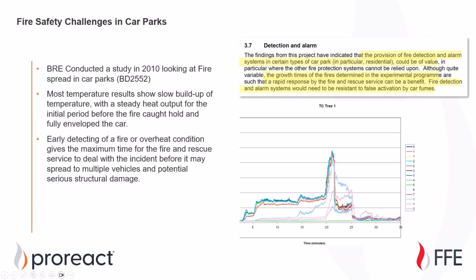And the British compliance body, BRE, had conducted a study that there is towards the first 5 to 10 minutes, even up to about 20 minutes, when you have scenarios like this, kind of a build-up period where your temperatures can be detected, like an overheat condition with linear heat detection, during these times to notify somebody that attention is needed in these areas, and potentially have saved this fire from becoming what it became and destroying all that it did. So linear heat detection is in the conversation with a lot of the development that's going on with codes and standards when it comes to parking structures.